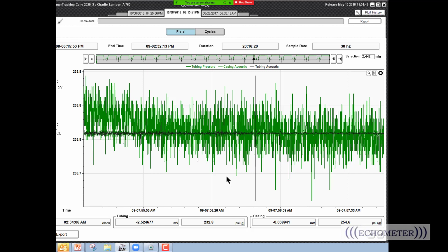You're limited based on the travel time, and every trip takes time. The longer time means fewer trips per day, and the less liquid you can carry per day. So a deep well means you have fewer trips. A deep well means you can only unload maybe 3 barrels of liquid instead of 10 barrels for a shallower well, because you can't make the number of trips to get the liquid out. So you're not limited by depth. You're limited by the time for the trips and how many trips you can make.